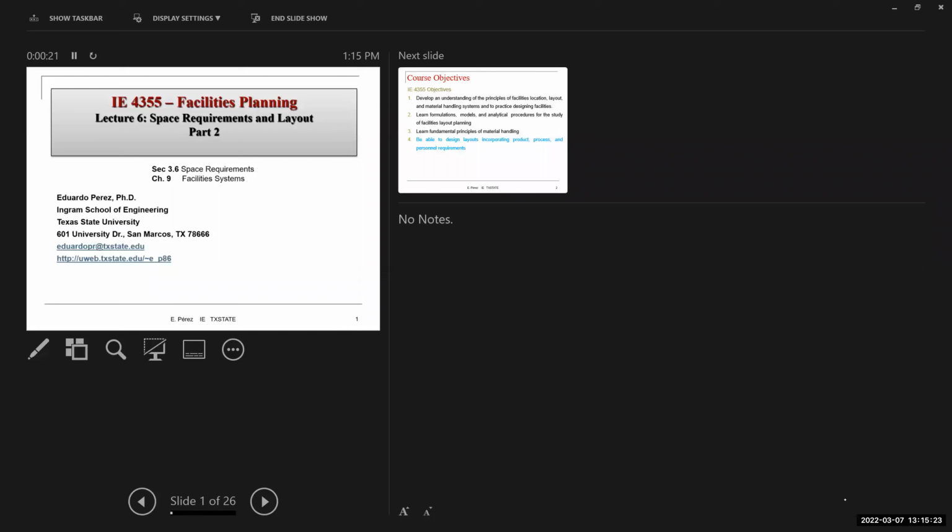Yes, sir. So with the information we just found out, that BTU rate, they can now give us an idea of what the size of the system is. Exactly. And now we can plan the space that we're going to use. So once you compute the cooling and heating requirements, they can have an idea of how much equipment you're going to need for this facility, and then they will tell you, you're going to need this much space to accommodate this equipment, and then you as a facilities planner will account for that in your design. Yes, correct. Good question. Any other question?